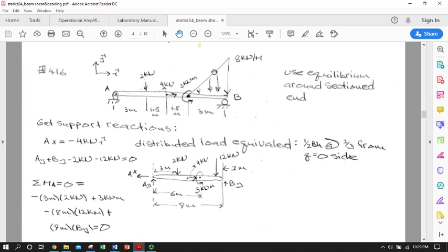We're going to want to get an equivalent position and load for our distributed load, so we're going to cheat a little bit, and we're going to use our triangle area under the curve relationship and say our distributed load equivalent is equal to 1/2 base times height of our load function here. So that's 8 kilonewtons per meter height, and the base being 3 meters, 1/2 of that. And we know that it's located at 2/3 of the way from here to here. So the equivalent of the distributed load is located really at x equals 8. So it'll be right about here.